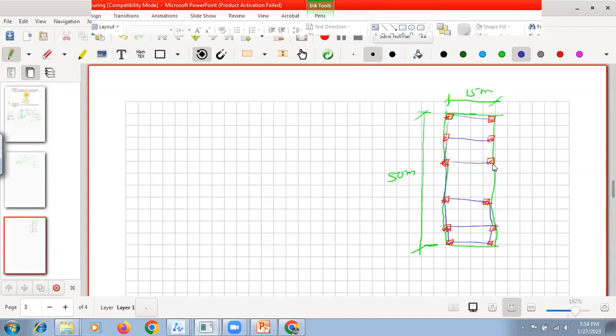At that time I was project engineer and I received the drawing from the structural consultant. This was the layout. Okay, what is our general process? The architect prepares the plan and sends it to the structural consultant. On the basis of the architect's drawing, he puts all the column positions, beam positions and everything. He designed the column. Okay, and the column sizes were 230 by 450. Some columns were 230 by 380.